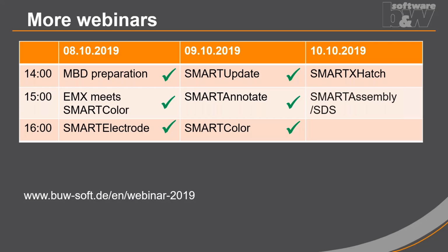And when you apply the rules again, we have seen that there was a rule that colorizes all of the surfaces in a specific base color. So you can attach to that base color in downstream programs a general tolerance, for example, and you make sure that there is no surface which has no color code applied. So if you have well prepared your rule set, then new geometry, maybe you create a new bore, will also be colored by the rule set. Just execute it, and your added bore will also be colored. And if it's another geometry which is not covered by the rules, then it will get colored by the base color. If necessary, the user can manually add a different color to it.